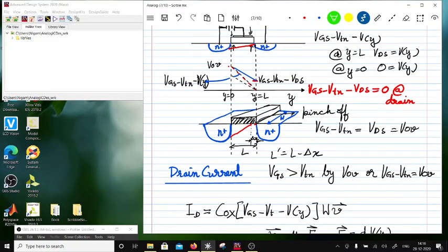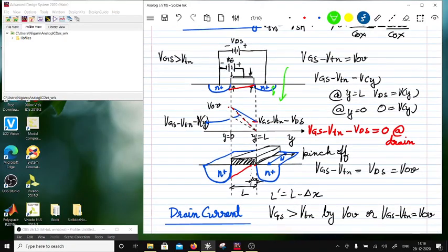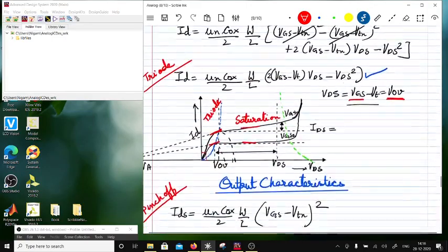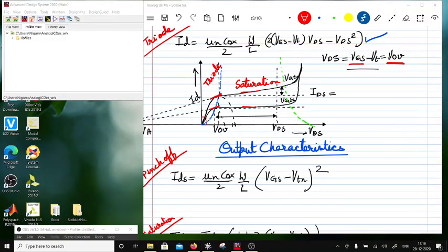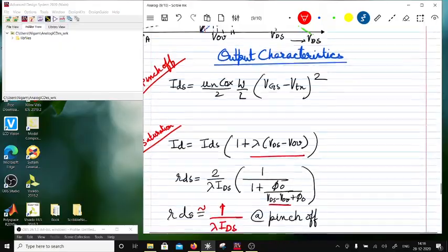So when the drain, this is the drain bulk junction, when this breaks down, all the current basically leaks to the substrate rather than going this way. Okay, so this is the major cause of the breakdown. That's why you are going to have an LDMOS, right? LDMOS would reduce this leakage current. Okay, so this region is basically the drain to bulk breakdown region.